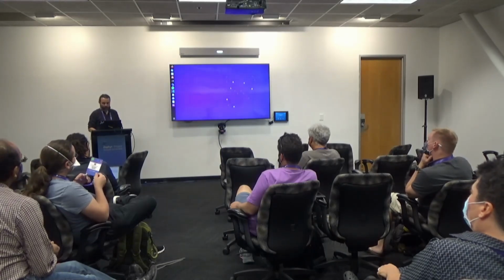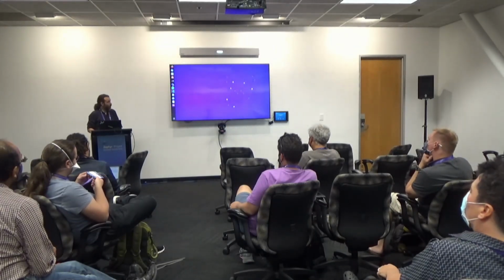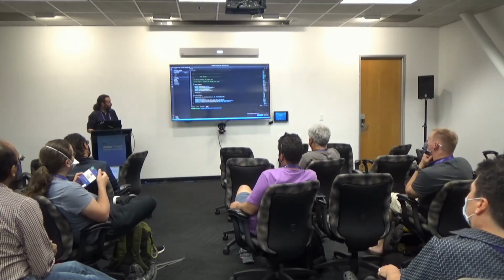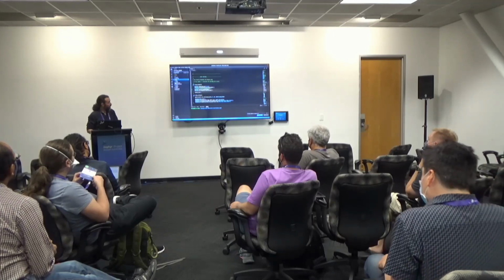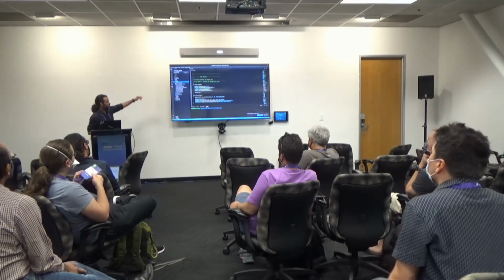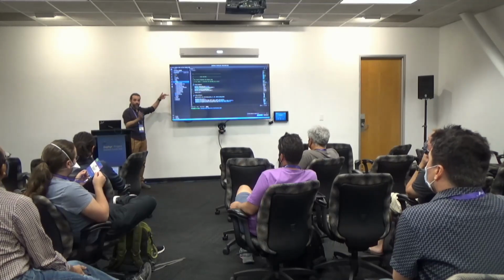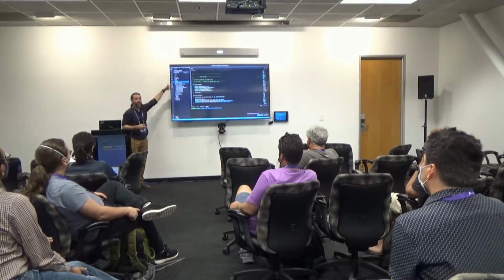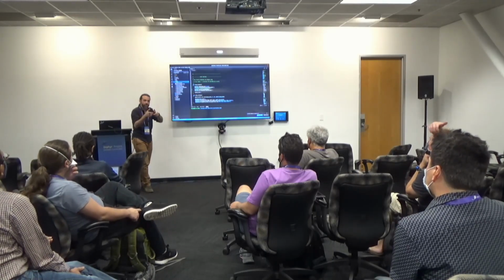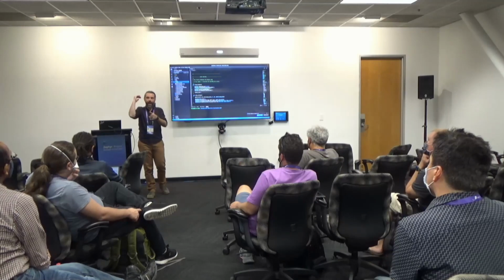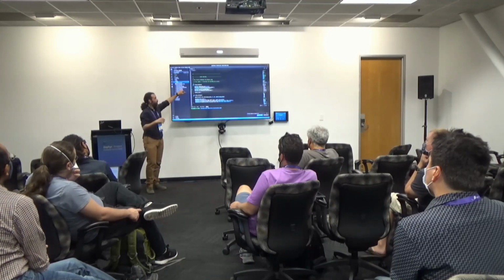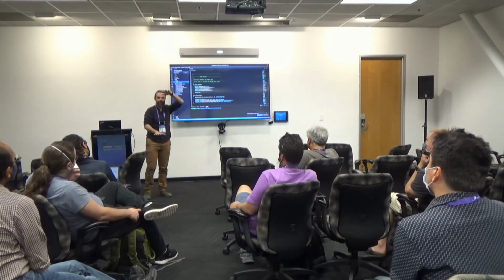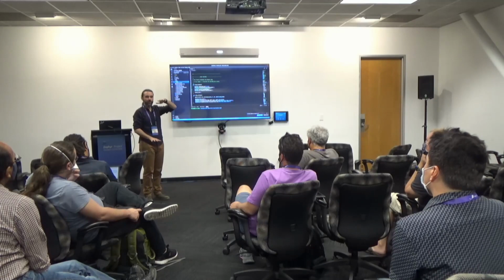What we have right now is Zephyr, and in it our modules, the different modules we had to write, which make our Zephyr flavor. In our ADC driver initialization, a hardware configuration overlay calls the right function depending on the kind of initialization you want.